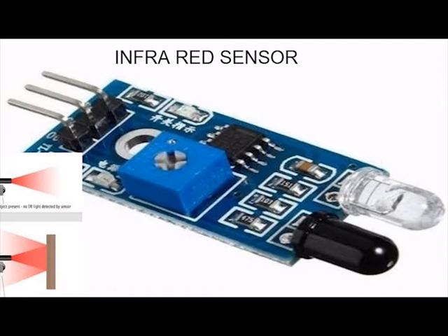We can also notice that the sensor has 3 pins, namely the VCC, where the 5-volt input voltage is given, ground, that is basically the cathode connected to the LED and the photodiode. Lastly, the output pin. The infrared sensor can be used both as analog and digital output sensors.